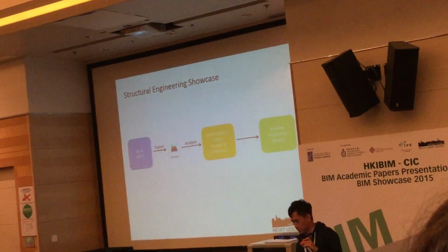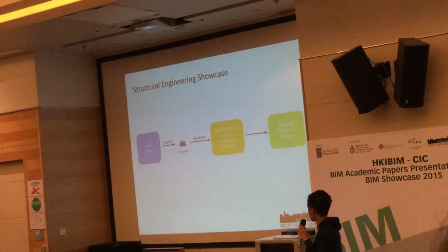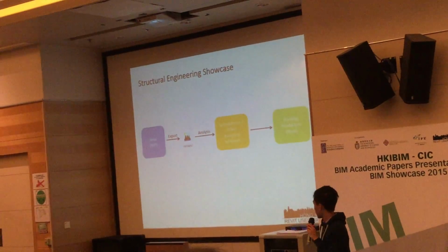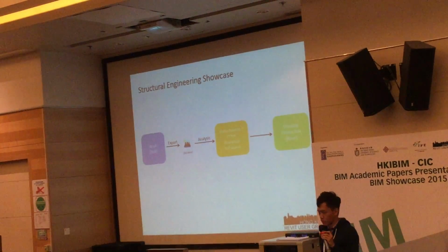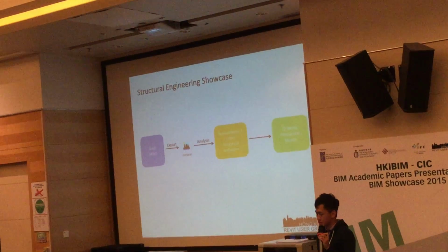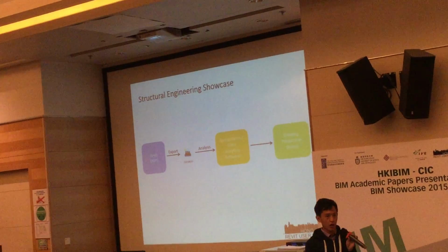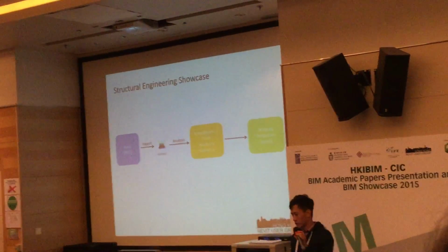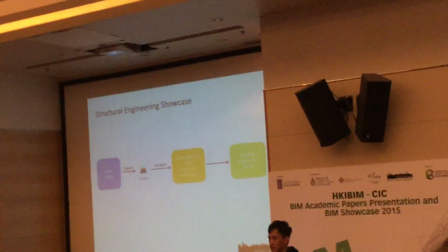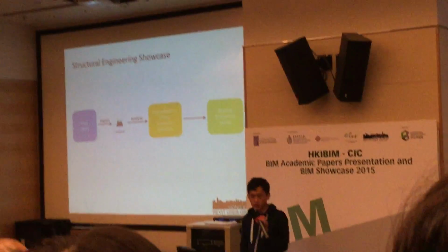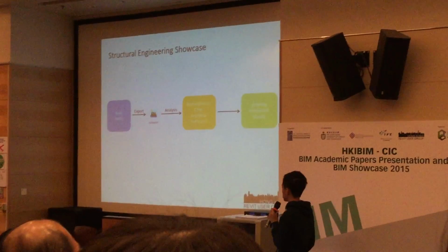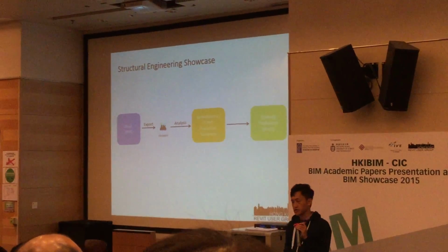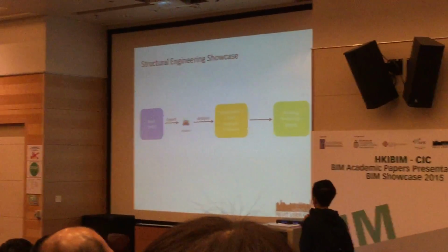And so that would be what a structural BIM workflow would look like. You have your Revit work in progress, and then you export to ETABS, do your analysis, and then pull out your analytical result to your spreadsheet, which is basically what you've been doing all the time. And then after you fine-tune your structures and member sizes, you go back to Revit and do your drawing.